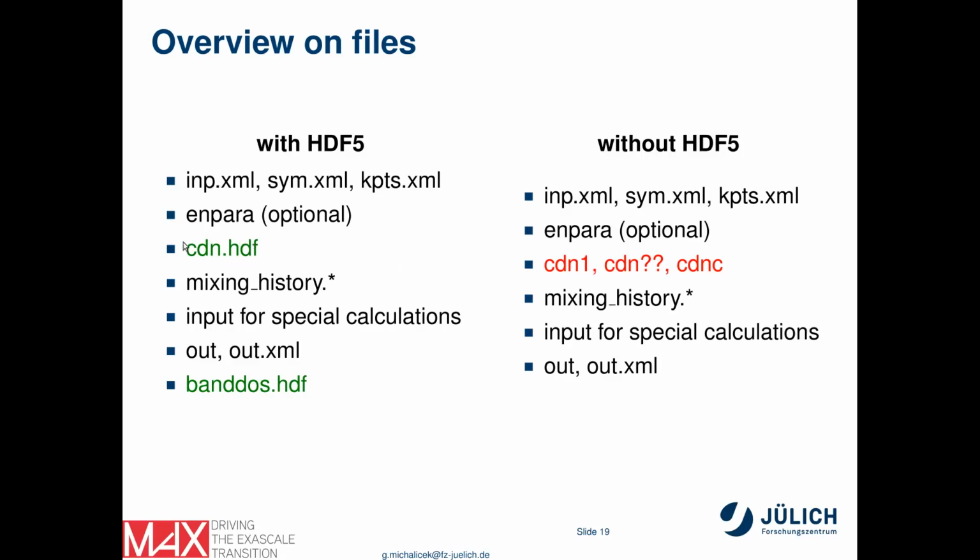So cdn.hdf contains the charge density, or without HDF5 it is cdn1 and so on. And I mark here the HDF files in green because they typically include some additional data that make the usage of Fleur more comfortable. Then you may also have some output on the mixing history.